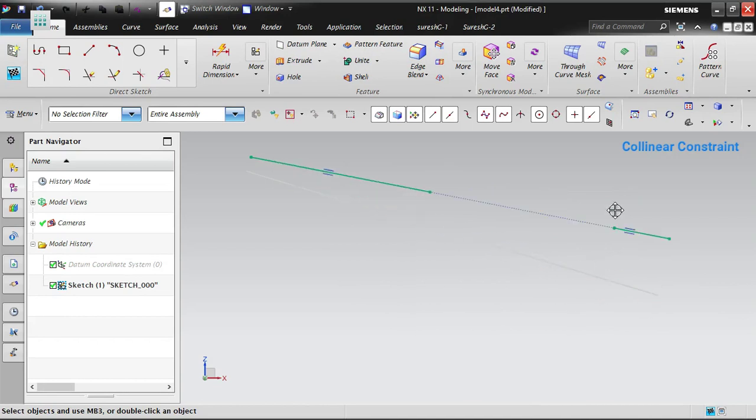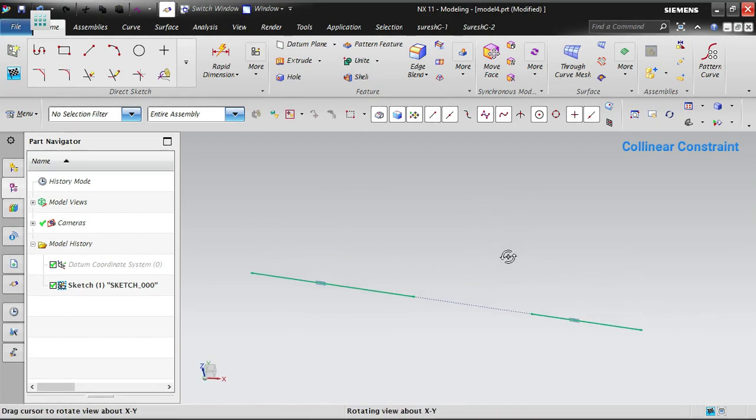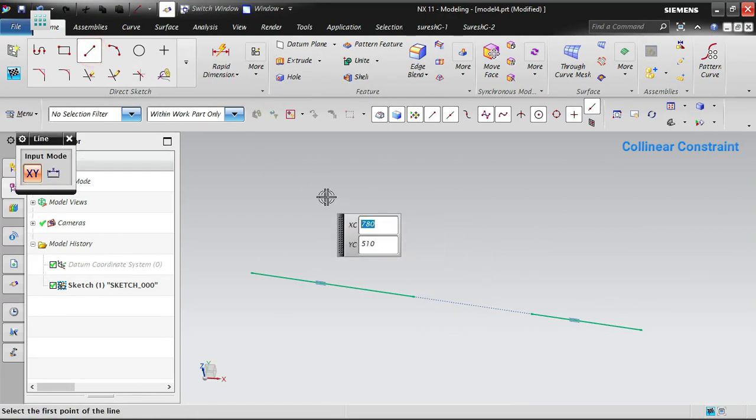Even though it is away from the other, it will align with reference to this line's angle only. Okay, this is different; vertical and horizontal alignment is completely different. Horizontal and vertical alignment work based on the end points of the line, but this will work based on the angle of the line, or else we can say, collinearity. For example, now I will do one more time.